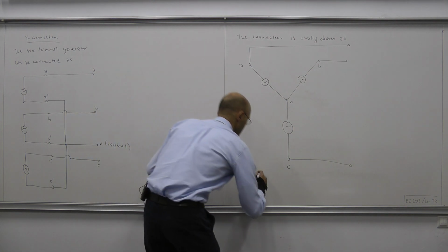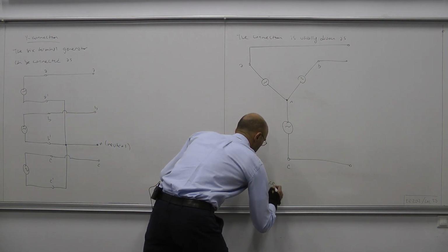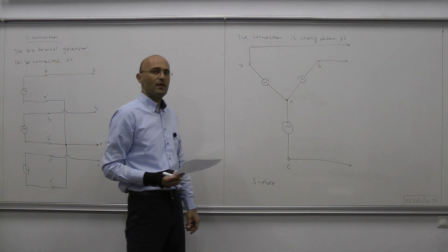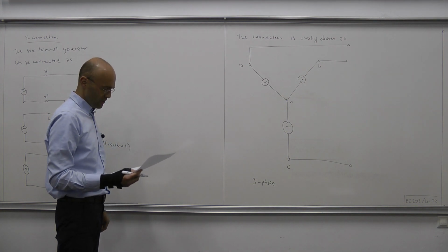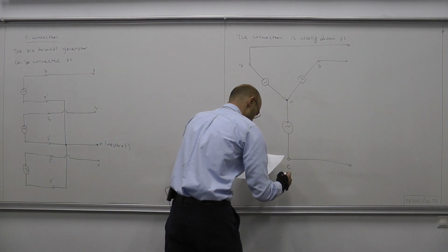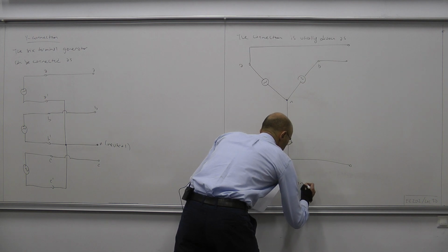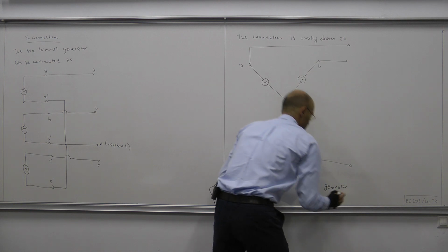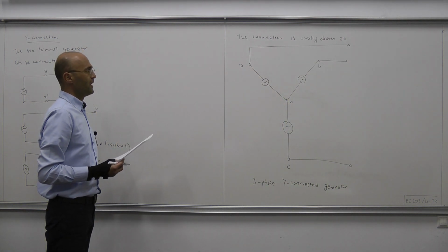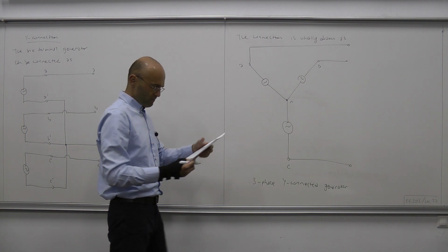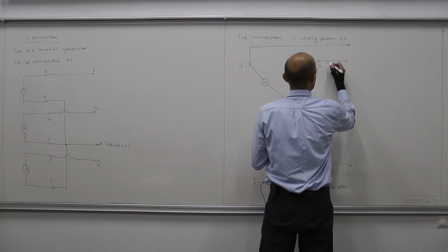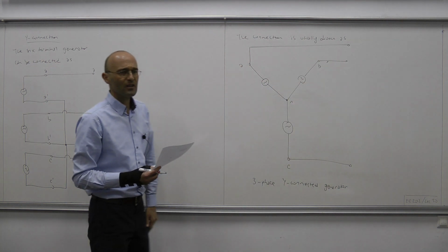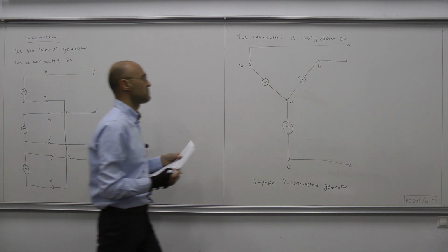Now this is how we represent, when we draw our circuits, a six-terminal AC generator. Okay, so this is called a three-phase Y-connected source or generator. Okay, now in this connection, the voltage between, so these are called now lines because those terminals are now touching the transmission lines.